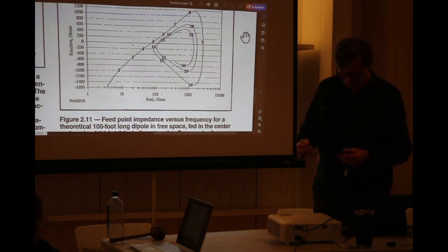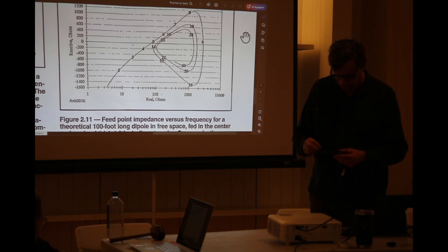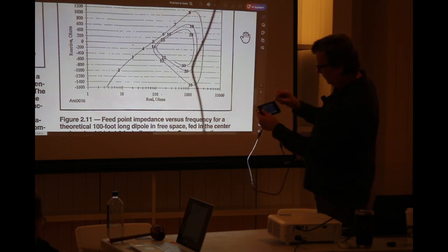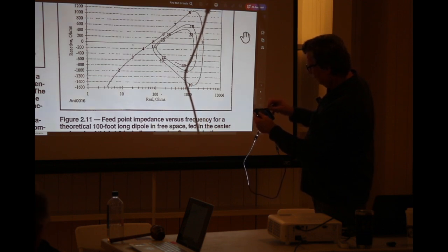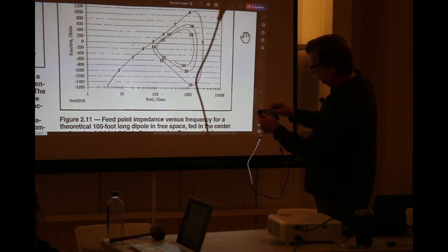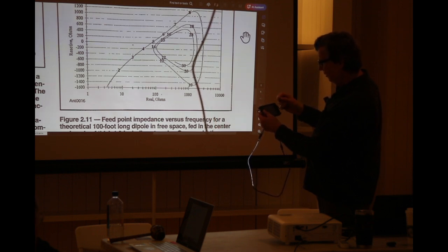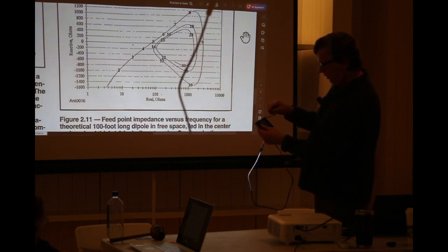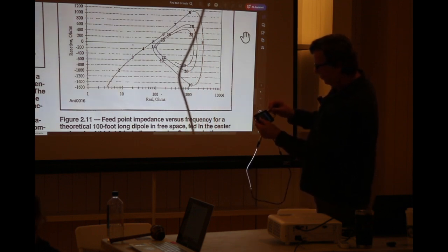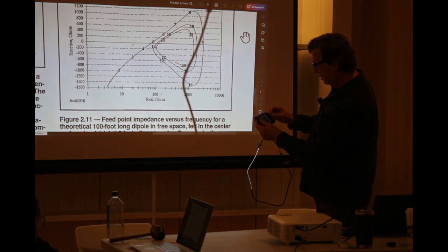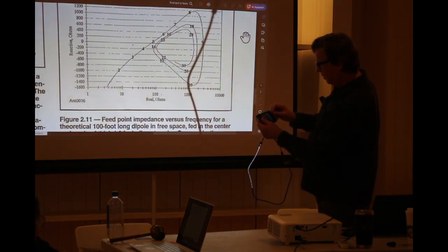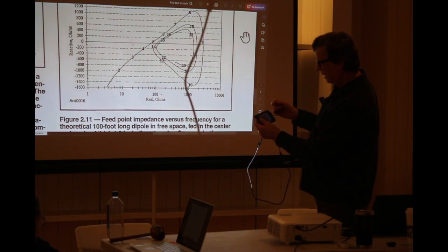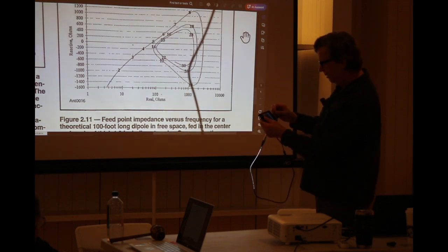So what we're going to do is, first of all, you do your stimulus. So you go between 3 and 30 megahertz. So you go to 3 megahertz. That's a good default, and stop at 30 megahertz. And that's a good thing. So we have an open circuit showing over on the right there. But we're going to use our 3-point calibration here. So you go back, go to calibrate, and I always like to hit reset after doing the calibrate. It isn't absolutely necessary, but it does help.